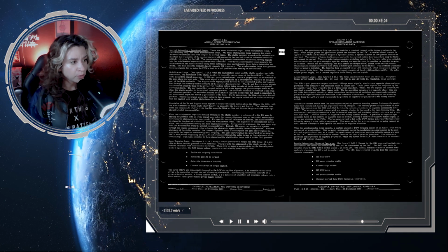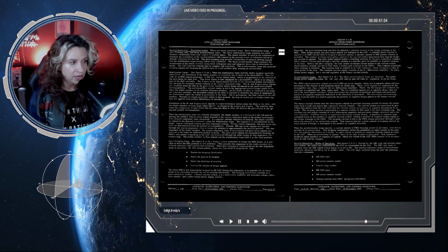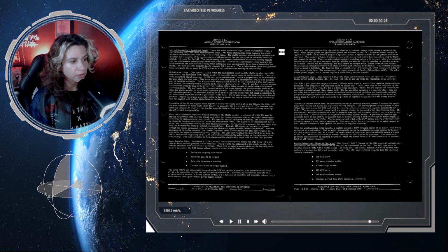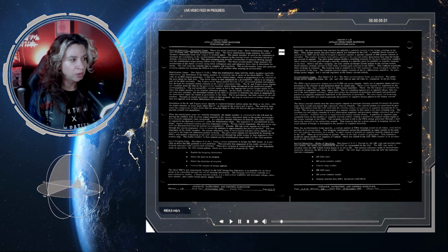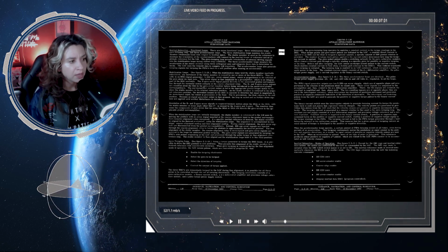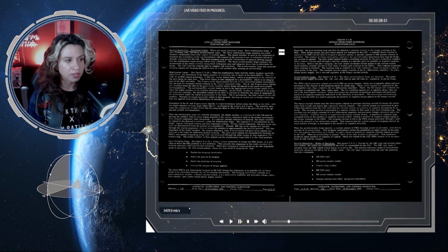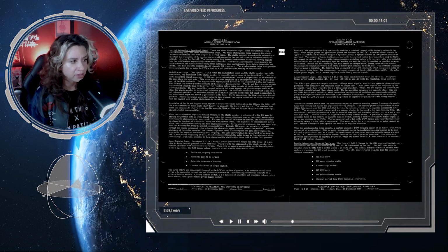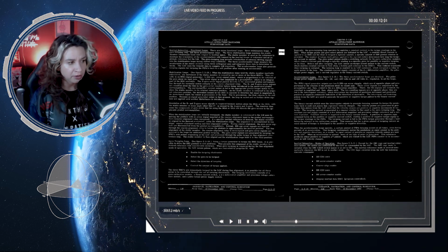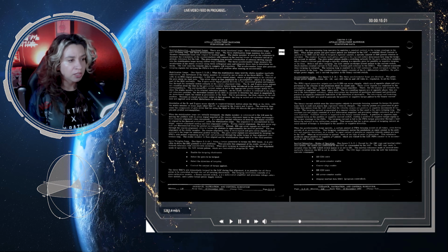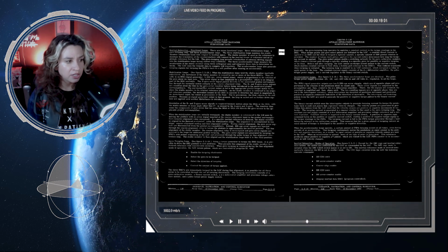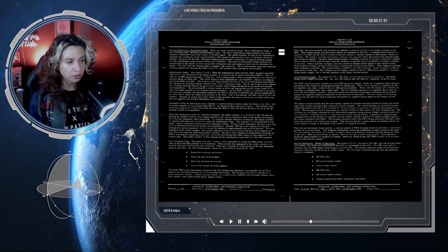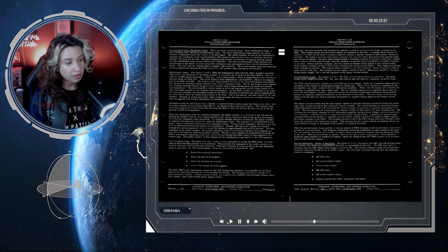Gyro torquing loop, see figure 2.2-10. Using a torque generator to torque the IRIG floats, it is possible to drive the IMU gimbals to a new position. This permits fine alignment of the stable member to a desired reference with considerable accuracy. When gyro torquing is required during the fine alignment mode of operation, the LGC issues pulses, which are controlled by program 52, that